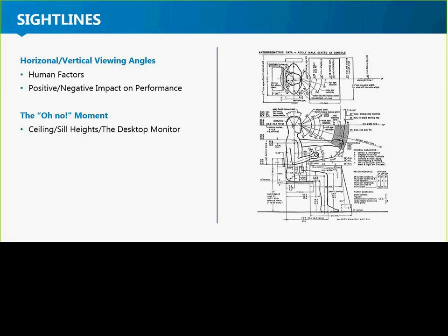But if you have any opportunity to work with adjusting ceiling heights in a room, selecting a room that has taller ceilings, etc., then know that ceiling height will drive what size video wall, and what that means is that determines what the bottom of the video wall panels will be off the finished floor, that allows your operator to see over the tops of the monitor to be able to see that video wall screen.